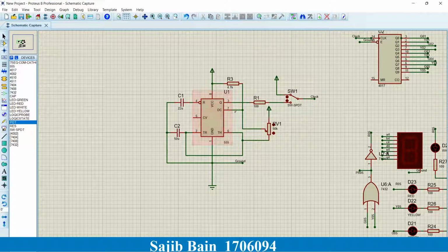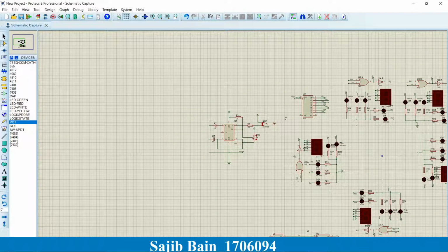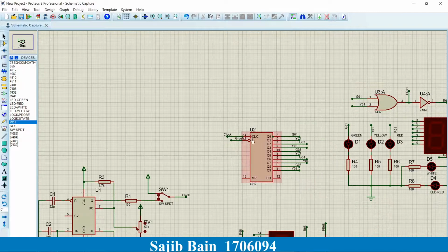The clock pulse is passed through a SPDT switch. One throw of the switch is connected to the clock and the other throw is connected to a power supply. And finally the pole of the switch is connected to the counters. The entire system can be paused and resumed by operating this switch.